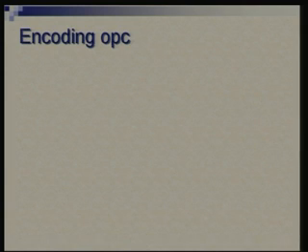OPC, if you recall, is a signal coming from the main controller and going to the second controller which controls the ALU. We said that all instructions fall in 3 categories. R instruction is one category, load store another category, and basically branch is yet another category. For jump it really doesn't matter.